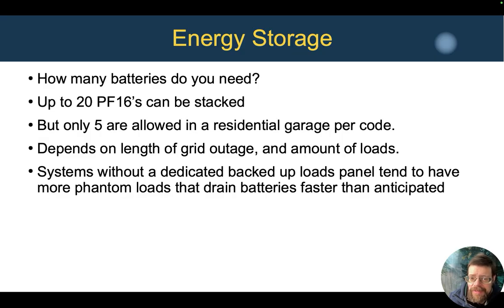Some houses with electric heat can easily be 100 to 200 kilowatt hours a day. So you can see 80 kilowatt hours doesn't get you very far there. This is an issue with all electric houses, which are becoming more popular. Even when we're looking at efficient heat pumps, it's still a much higher electricity demand than a natural gas or propane heated house. So it becomes a lot less able to do backup power for that house with reasonable size of battery banks.